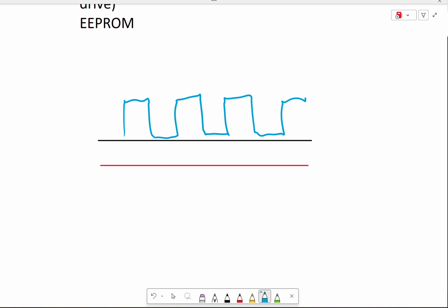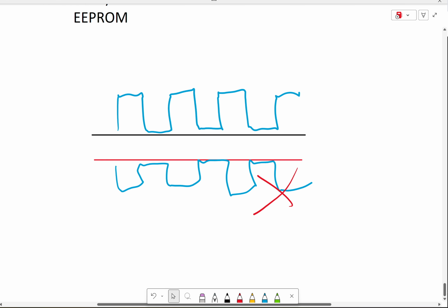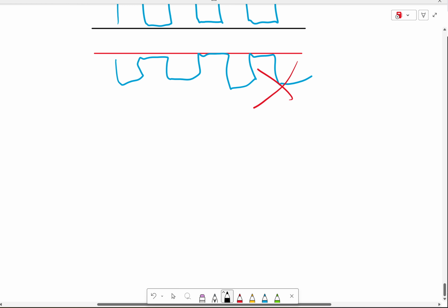And if you have a rising and falling magnetic field, those magnetic lines of flux around that wire are also going to interact with any adjacent wires in the harness. Sometimes that doesn't matter. Sometimes it does. Specifically if you have data carrying wires, where this may induce a little bit of current in that adjacent conductor. And this we don't want. So if you have two wires lying parallel to one another, then yes, you can have that interference happening.